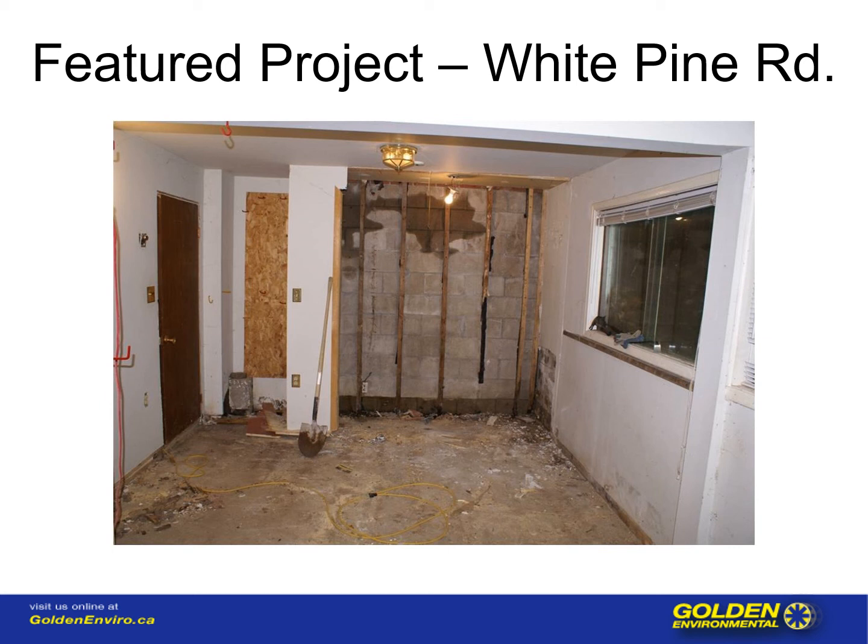Also note that on the outside of this wall where the tank sat, we did dig out the immediate impact area where the 900-liter oil tank sat. We dig down to get the oil saturated soil out of there to stop further migration, but we do not dig down so far as to compromise the building. You can also see along the very bottom of the concrete block how the oil has seeped through there as well.